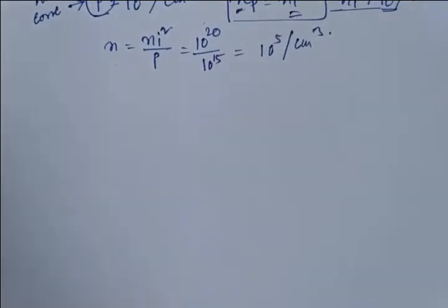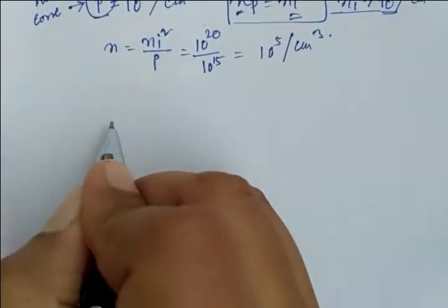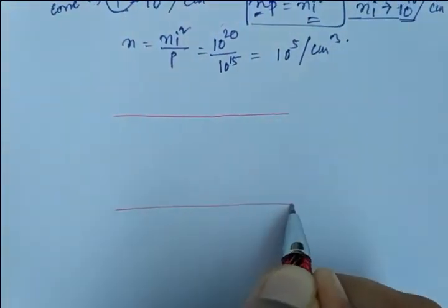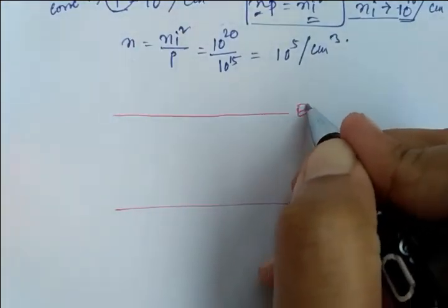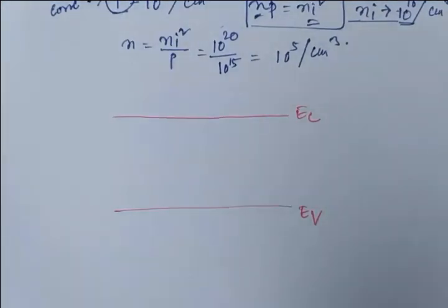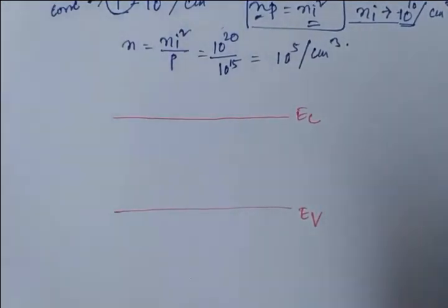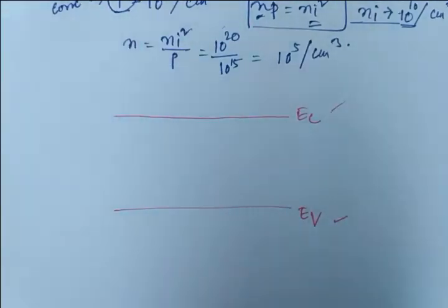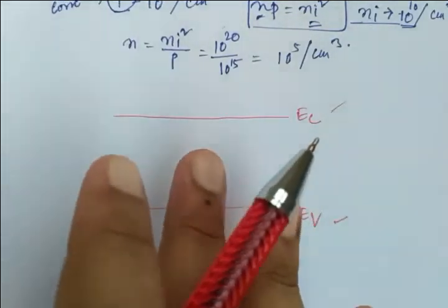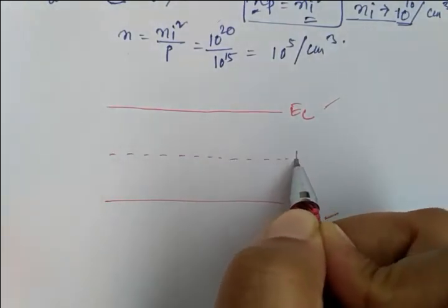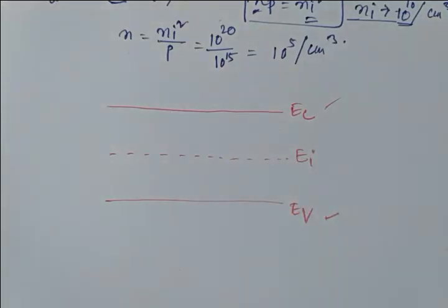Okay, let's come to that point. I think it's visible. I am just drawing this part, and please try to draw this section according to my way. So this is your semiconductor. I think it's a p-type doped semiconductor, right? And how can you define a semiconductor? Obviously, in terms of energy level, there is a conduction band and a valence band. And if there is no doping, what is your intrinsic energy level? Yes, this is the 50-50, in the middle portion. This is your EI, okay?